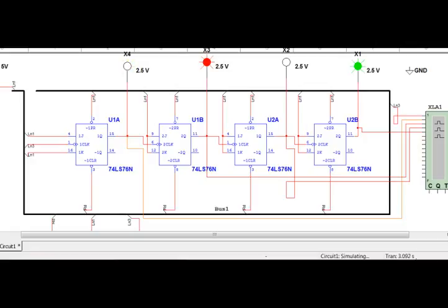It's about 20 seconds to get 1 second in. It takes the computer time to simulate the problem. So the time of the problem is generated on the bottom of your Multisim, telling you how fast you're going in real time. That's why I can put 10 hertz and see it flashing at less than a 1 second rate.